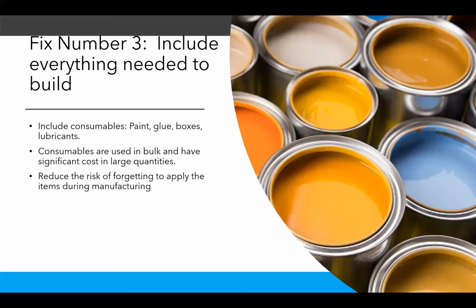And be sure to include all the things that you're currently using as consumables, right? That could be screws, rivets, again, paint, primer, even tooling, right? A lot of times people don't include the tooling involved, or the drill bits, or the other products that may be consumed during that process. And a tremendous amount of cost can go into a product if you're not accounting for those things.